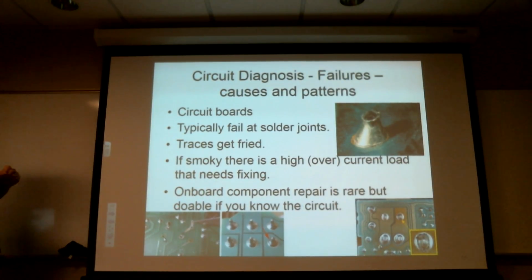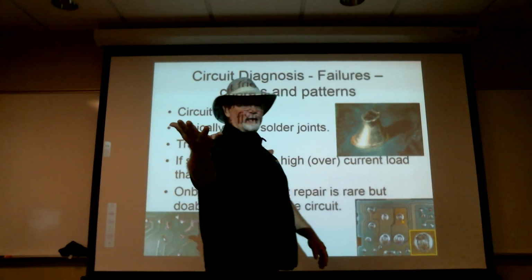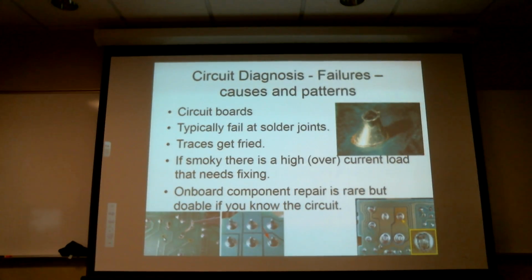The way these circuit boards are made is they take and make a piece of fiberglass, okay, a bunch of fiber, lay out a bunch of laminates, impregnate it with epoxy, turn it into a nice hard board. They then glue a layer of copper on it. The copper is bonded onto it, and then either using acid etching or now laser, they remove all the copper except for where the wire traces and pads are. Okay, remove all of that off, and so if you get this pretty hot,